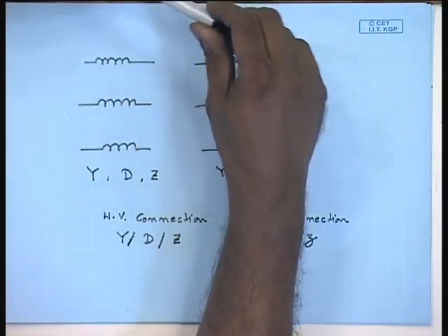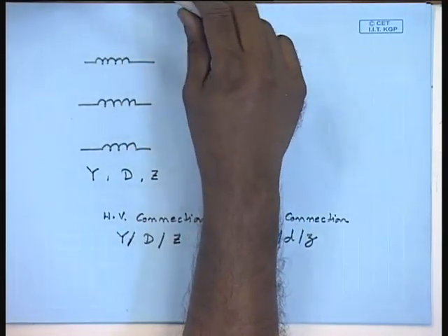In our last lecture, we have seen how to find out the line voltage and current as well as phase voltage and current conversion ratios of a 3-phase transformer given the winding turns ratios. So, we have seen that the voltage magnitudes on either sides are different. That is the purpose of the transformer. However, a closer scrutiny will reveal that not only the magnitudes of the high voltage and low voltage sides are different, in many cases they are also not in phase.